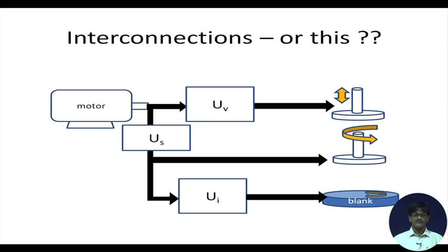Since we can move very fast through it now, we can say here, if UV is connected to the motor and US is also connected to the motor directly, something is going to go wrong. What exactly? Suppose you change UV now, number of strokes get, say, doubled, but US is not affected because it is drawing power from the motor directly. So, millimeters per minute divided by strokes per minute, that is again going to become half. Is it going to affect the number of teeth being cut?